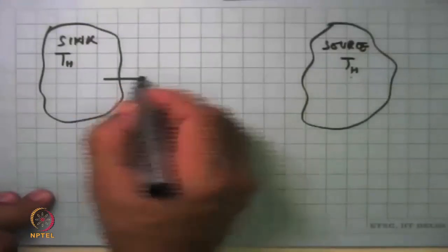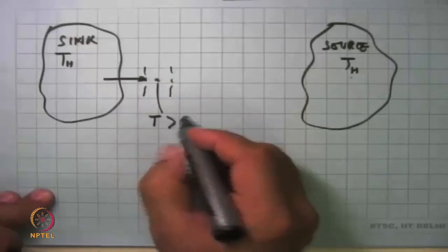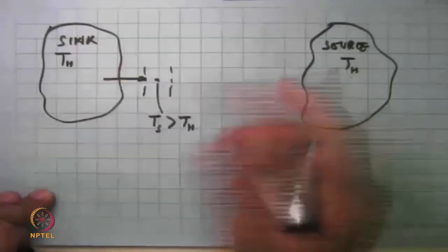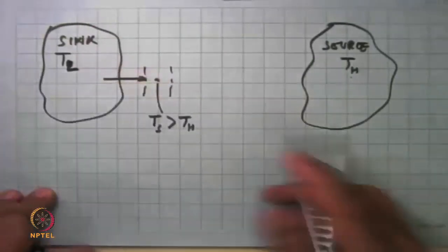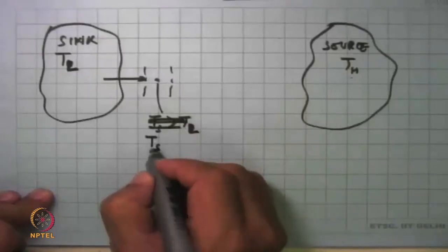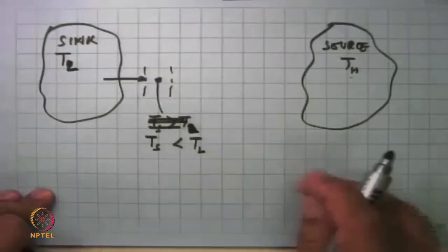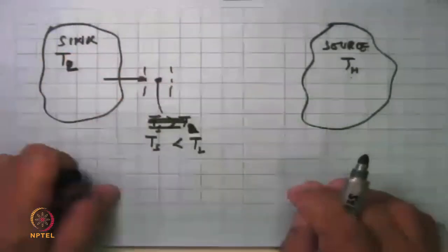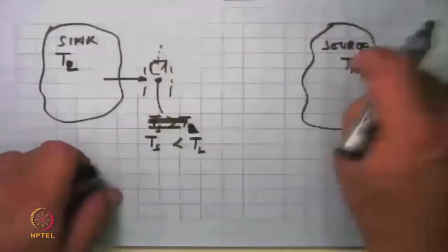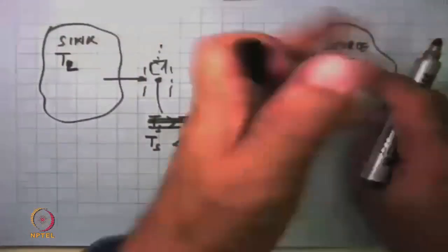This can exchange heat only with a system whose temperature here is greater than TH. So the system temperature at this point has to be, this is TL, less than TL. That means the temperature here has to be less than this temperature. Then heat will come here. Then this substance is now already at a lower temperature, it cannot give its heat there. If we throw it into this at the end of it, it cannot do it a second time then.